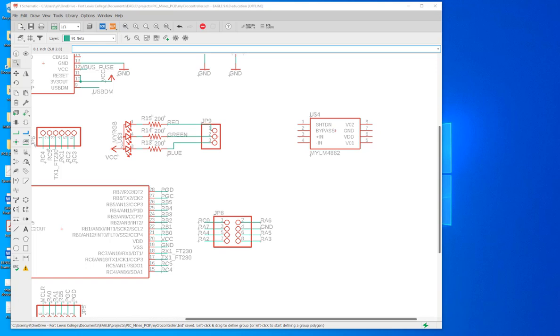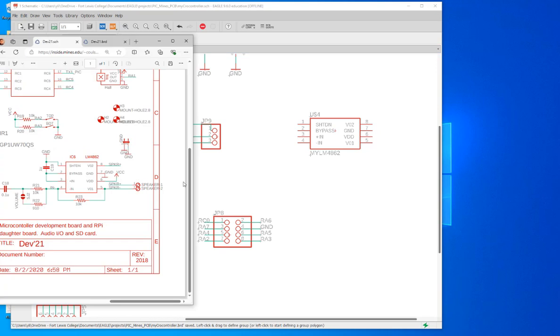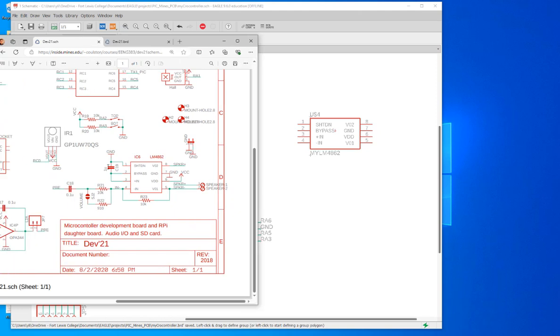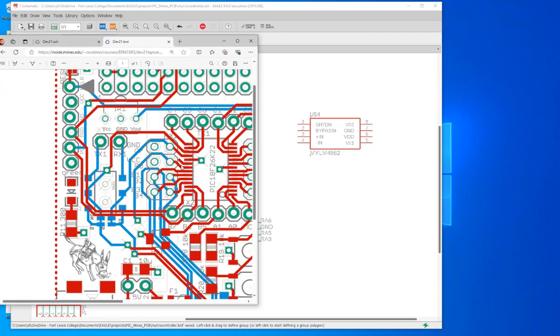So for the audio amplifier, if you come back to here, you can see you have how many? 1, 2, 2 capacitors. 1. So this is not actually being used. This is a connector. I don't think this is shorted to it. So it's just the 1 and 2 resistors and connector to the speaker. That's it. And the speaker's positive pin is not connected to anything. It's just basically VO1 connected to the negative pin of the speaker. Right? It's 2 terminals. If you come back here, you'll be able to see.